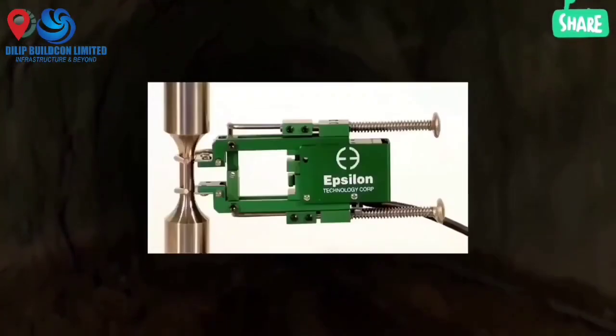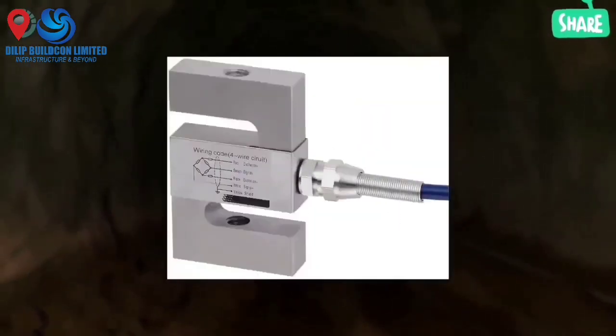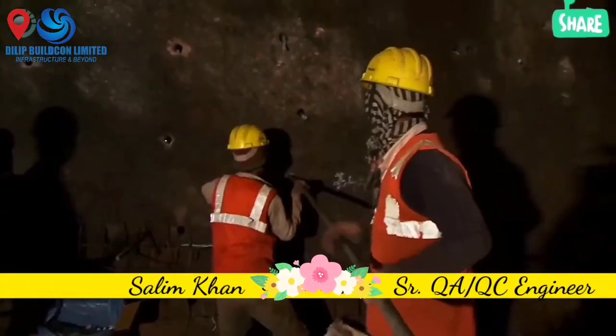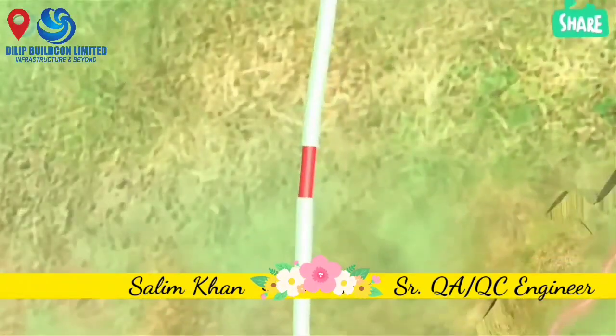Monitoring of critical aspects with instruments such as extensometer, pressure cell and load cell is carried out after every 10 meters of tunneling. If there are any variations or problems, adequate steps are taken to correct them, like changing supports and so on.